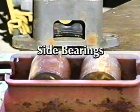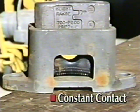Side bearing problems can also cause excessive truck turning resistance. Constant contact side bearings that are worn or improperly set up usually have a greater potential to cause excessive truck turning resistance. For example, if a constant contact side bearing is set up at less than its recommended height, it will apply excessive pressure to its wear plate.